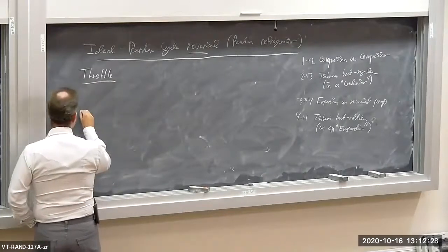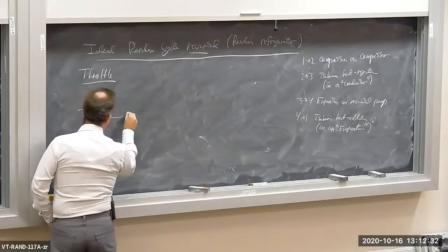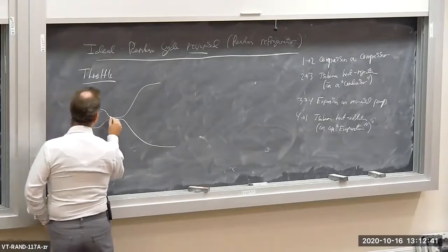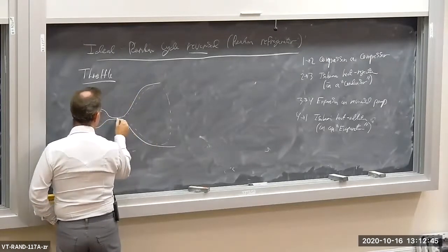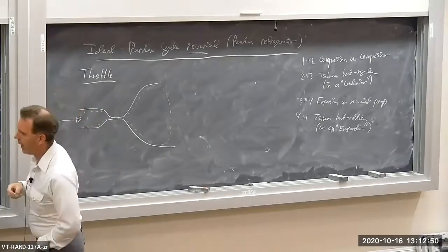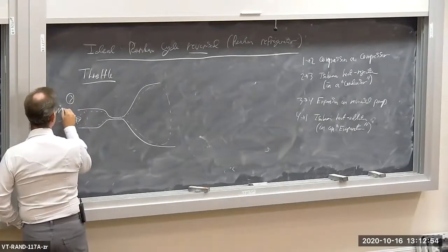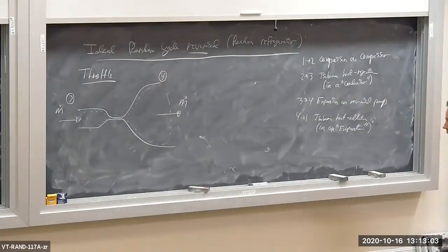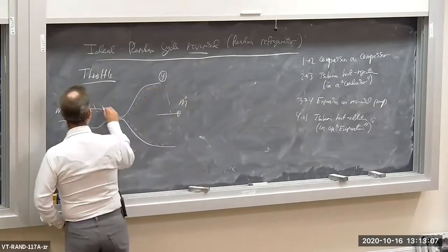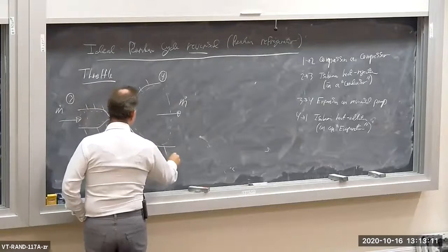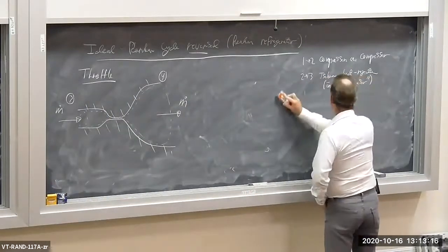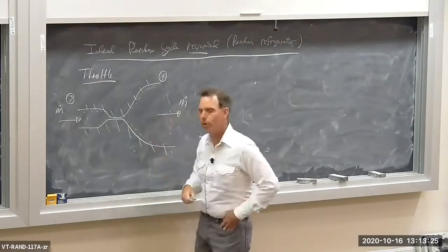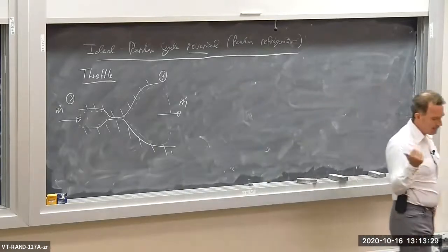What is a throttle? Well, a throttle, and again, I think we did an example, is a restriction followed by an expansion. It's a restriction in the flow or a pipe followed by an expansion. So here's our control volume. Mass flow comes in at, in our case, location 3. So we have an m dot, and then mass flows out, m dot, and we end up with state 4, according to our diagram there. Now let's say this throttle is adiabatic. Let's say it's insulated. If I apply the energy balance to this thing, it's an open system, single inlet, single outlet. You see any wires in here, any turbines, any boundary work going on? Nope, there's no work going on, no heat transfer. If we neglect kinetic and potential energy changes,